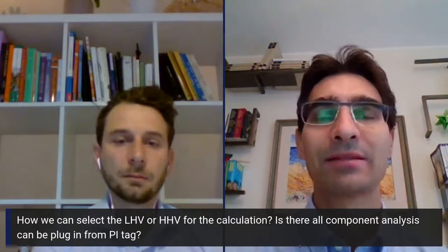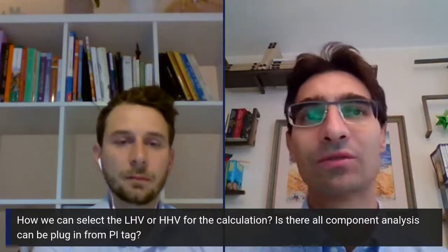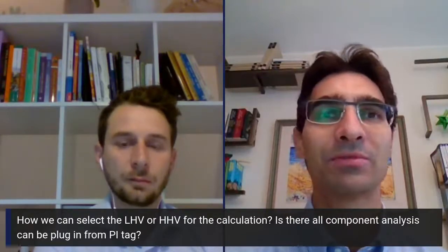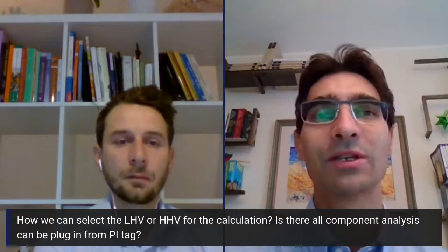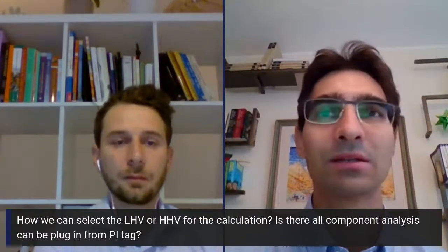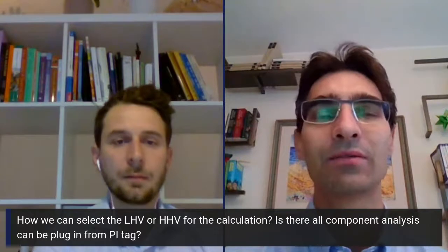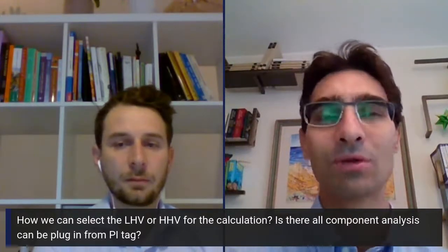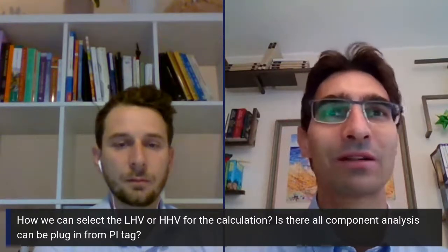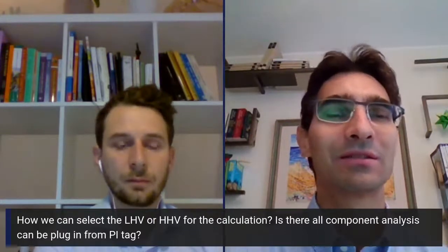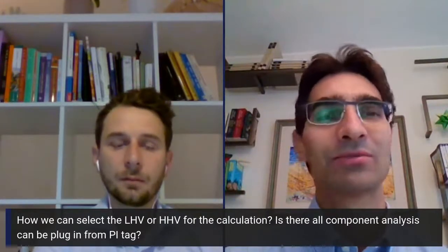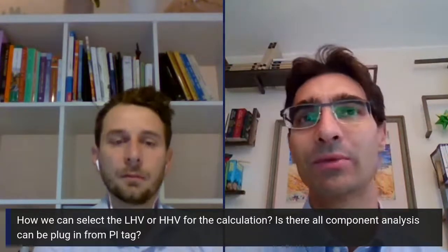So you get in Sigmafine, connected to the historian, the composition, if you have an online analyzer, for example, that is providing it, and then we have the calculations to get the desired information. So it could be LHV, HHV, could be molecular weight, as we said, compressibility factor, or something else. So technically it's what we call a data reference that we provide with the software. Okay.